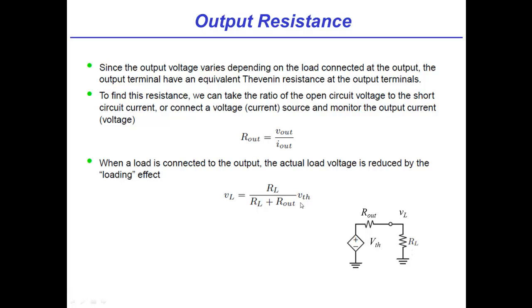That's right. It's like saying that we want the output side of the amplifier to look as much like an ideal voltage source as possible. Now, it's worth pointing out that this is a limiting factor in many modern amplifiers. The output resistance is not 0. Right, sure. It's some reasonable number probably.